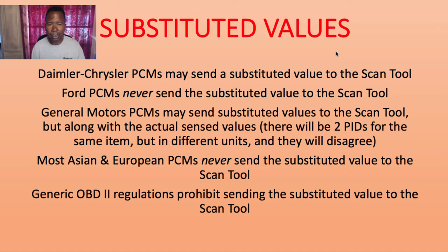Now let's look at this slide here. Chrysler PCMs may send a substitute value to the scan tool. Ford PCMs never send a substitute value to the scan tool. GM PCMs may send a substitute value to the scan tool, but along with the actual sensed values, there will be two PIDs for the same item, but in different units, and they will disagree. That's another clue also. Most Asian and European PCMs never send a substitute value to the scan tool, and generic OBD2 regulations prohibit sending a substitute value to the scan tool.